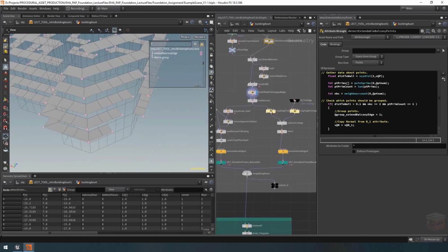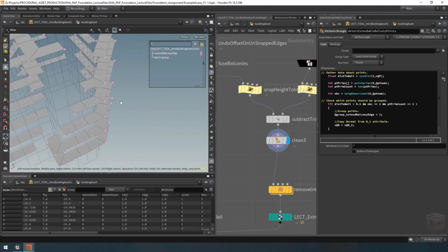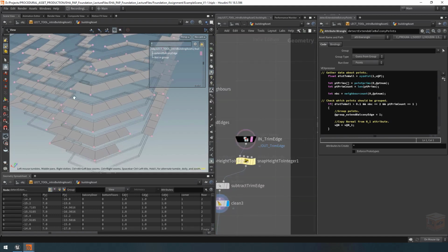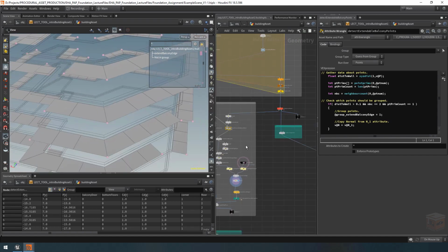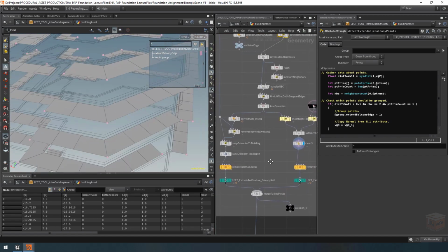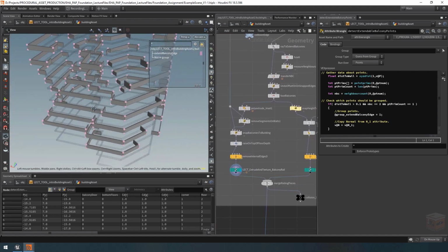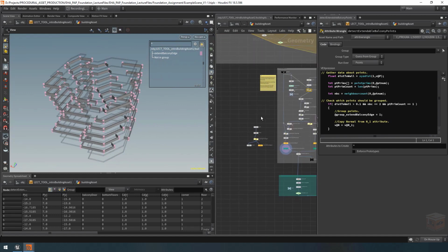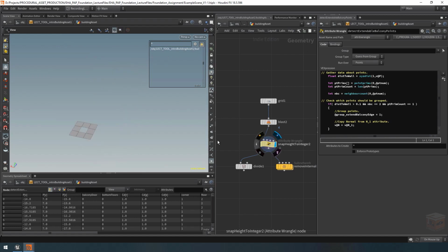And then finally, we need to do a little bit of final cleanup. So over here, we need to make sure that they don't intersect with the trims that are already on our building. So that's these shapes. Otherwise, we'll have intersecting geometry. And likewise, we need to make sure that in case our building is completely surrounded by balconies, we don't get weird issues. And that has to do with how whole polygons are dealt with in Houdini. And for that, I'll show you a quick example here.